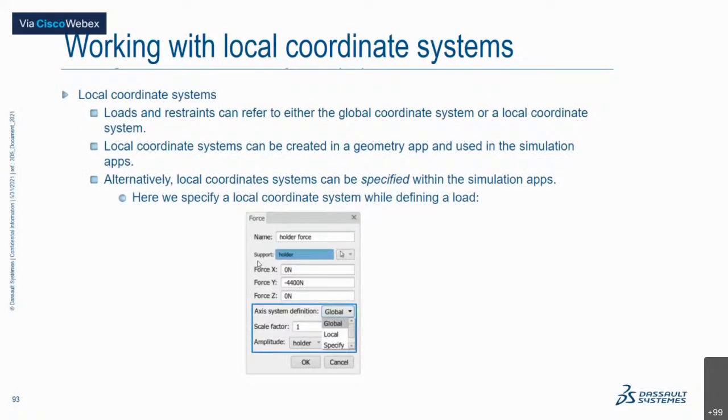And again, working with local coordinate systems. The coordinate system is also important while you're doing the simulation. If it's a force that you're applying, the force can be applied either with the global coordinate system or with a local coordinate system, or you can specify the coordinate system in which you're trying to apply it. So this needs to be taken care of when you're applying the loads.